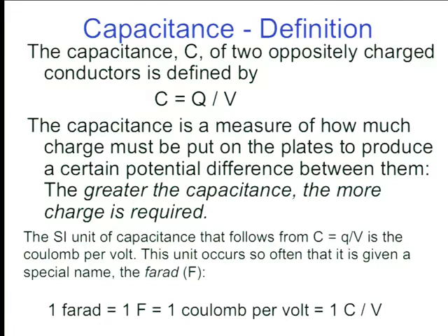But the voltage on the capacitor is that. Okay, just for fun, let's put down the voltage on the resistor. Anybody want to guess what that is? The voltage on the resistor is V equals IR, R of the resistor. Now here's the current, so the voltage should track with that. So it should do something like this, right? Because at the beginning, a lot of current flows through this capacitor, and in the long term, there's an open circuit. The current goes to 0. There's no voltage drop on the resistor. Okay, this is in your book, I think, but I want to move on.